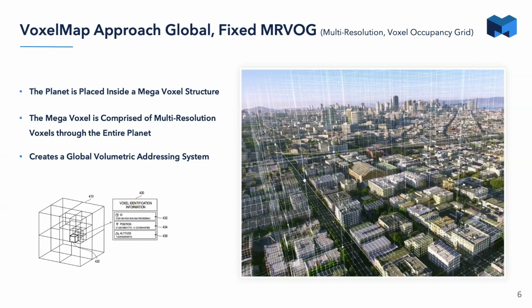So we primarily do that using LiDAR. If we pass a LiDAR sensor through the environment and it's firing its laser beams, if a laser beam passes through a voxel and it's not reflected off anything, then we label this as free space. But if the laser beam hits a surface and collapses down to the smallest unit of the voxel, we label this as occupied. So what we're doing essentially is we're etching out the matter of the planet and creating this very accurate model.